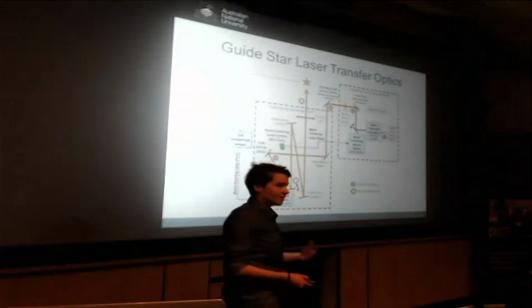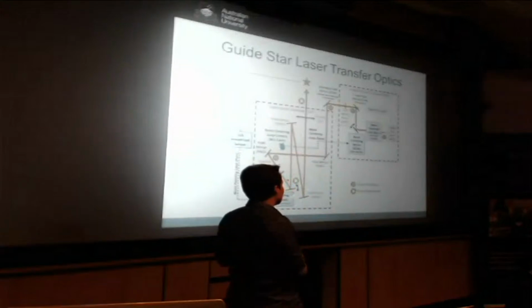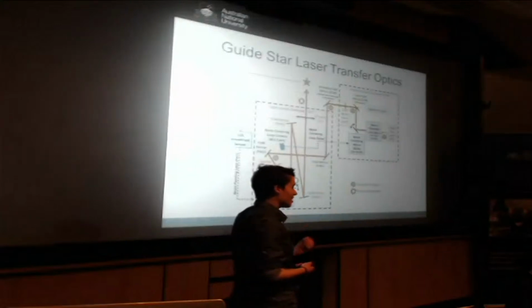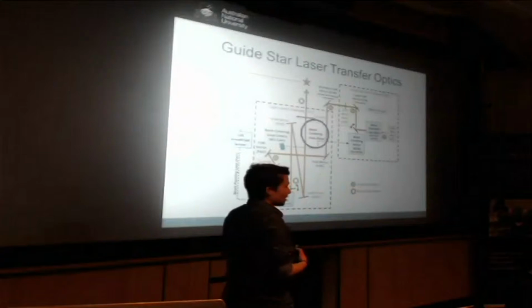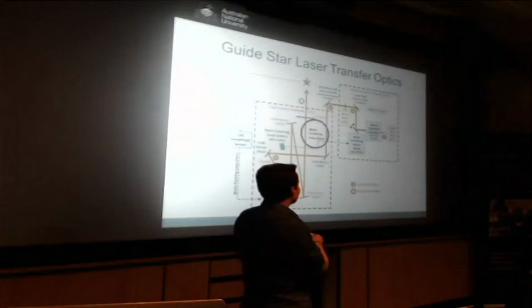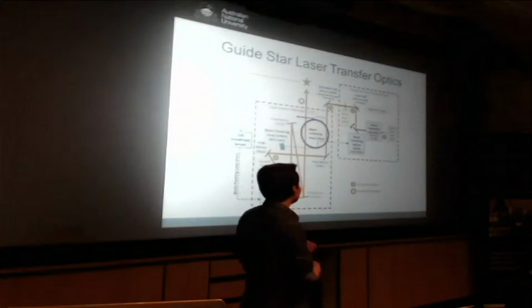And it is crucial that the laser beam always remains correctly aligned on the beam pointing mirror, or BPM, this component here, as this is what ensures that the laser beam is aimed towards the correct part of the sky. This is where my work comes in. So over the last 2 months, I've been working on the development of this beam centering wheel here, which is used to ensure correct alignment of the laser beam on the BPM.